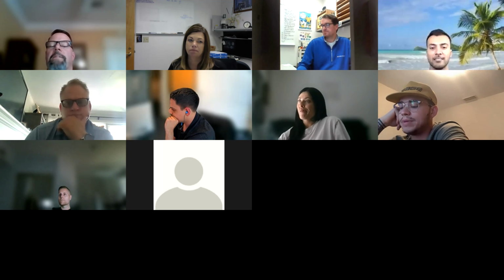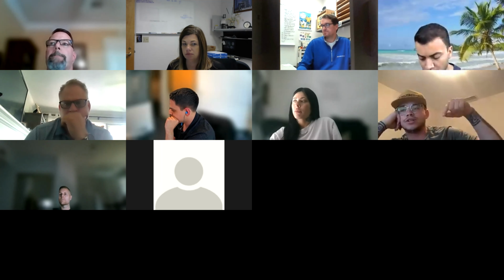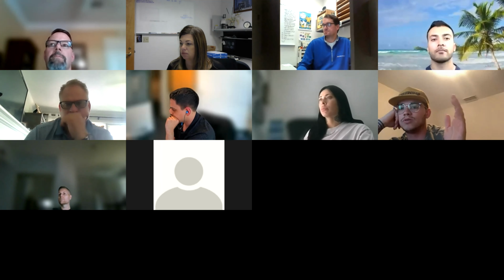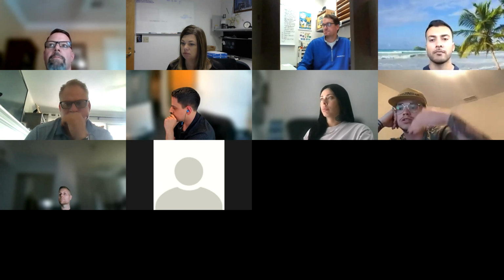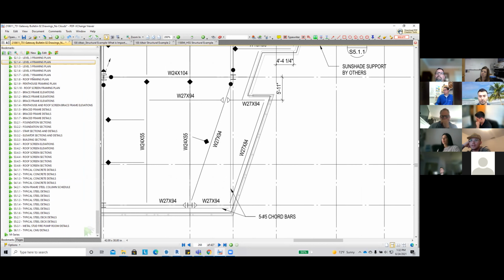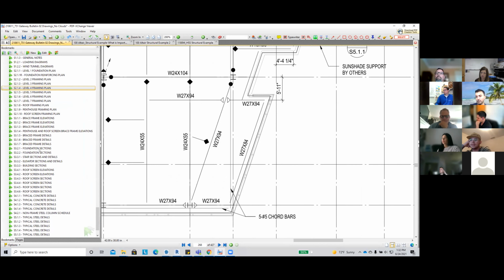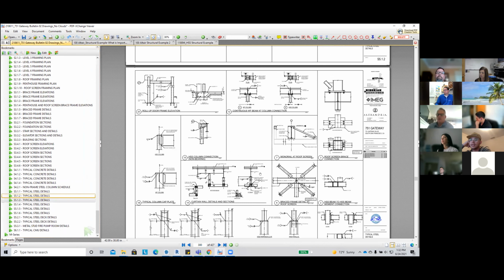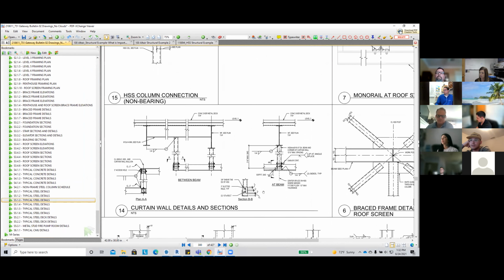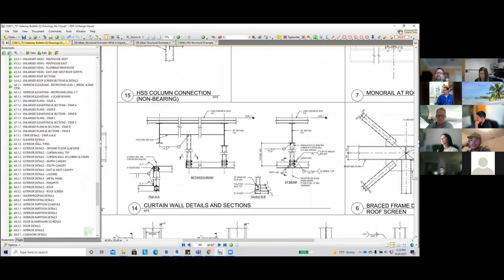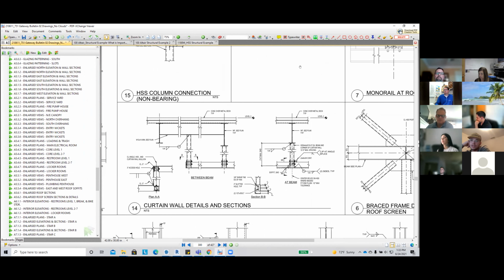Yeah, well, we're wrapping the beam, but the architect determined the dimension of the fascia part that wraps the outer beam canopy. And in order to make that happen, we had to draw a smaller steel tube. But we just drew the one that would fit the size of panel that the architect wanted, instead of making a big deal out of it and raising your hand and saying, hey, we changed the size of the steel here in order to get the panel fascia dimension that the architect wants. We just put a small little note that said verify, and I didn't verify it, which I should have. It was just something that I missed.